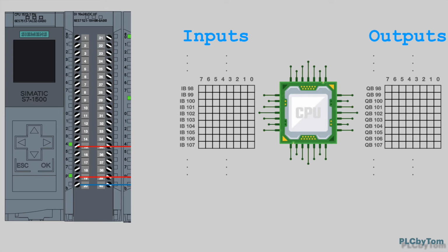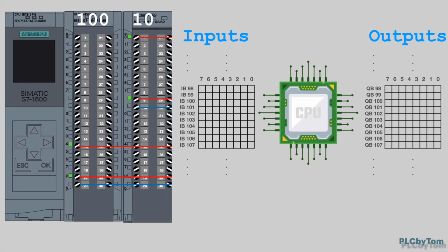In our example is digital input with 16 channels which requires 2 bytes, same for digital output module. For each I/O module shall be defined start address, and distribution of addresses to channels shall be checked in user manual of the I/O module. For example, the digital input module start address is 100 and the same start address for digital output module.